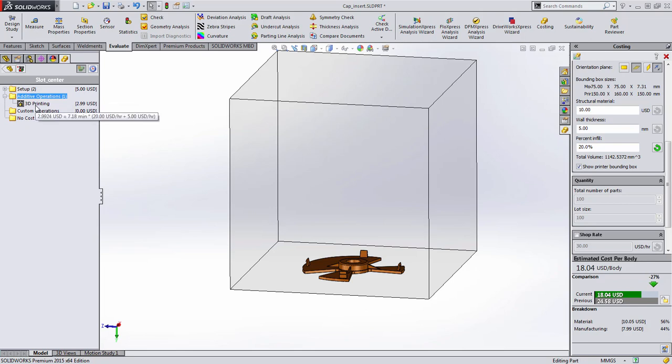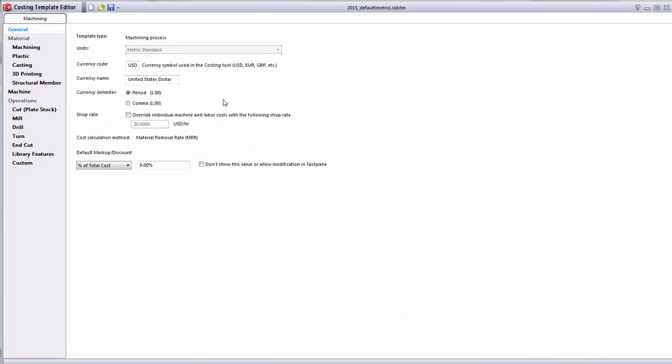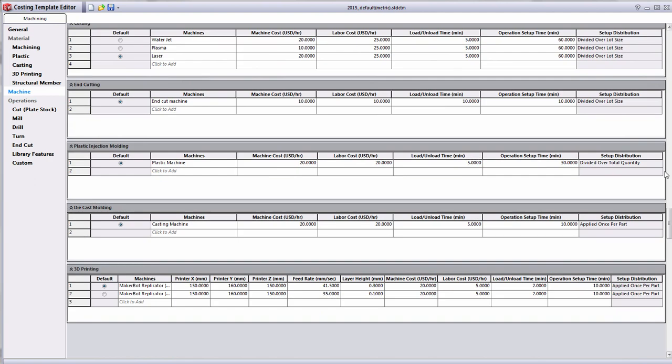You're able to toggle between different 3D printers or different printer configurations to evaluate not only the print time, but cost associated with generating the parts. All of this is rolled up for the multi-body part to account for the costing of all of the components. The templates are fully customizable for adding and specifying the different options on the 3D printers. In this case, you can see the difference between the speeds and layer heights for the different resolutions.